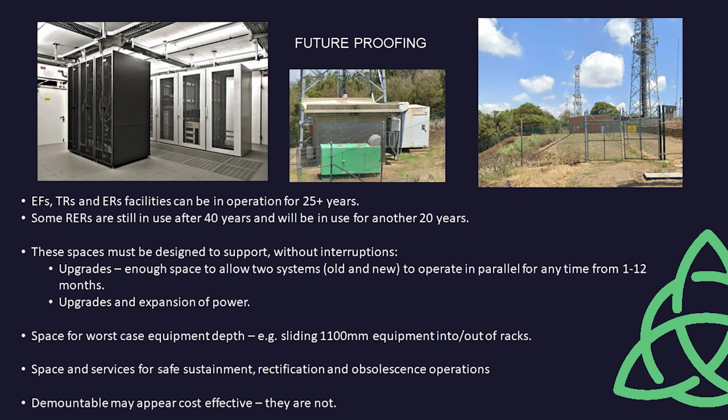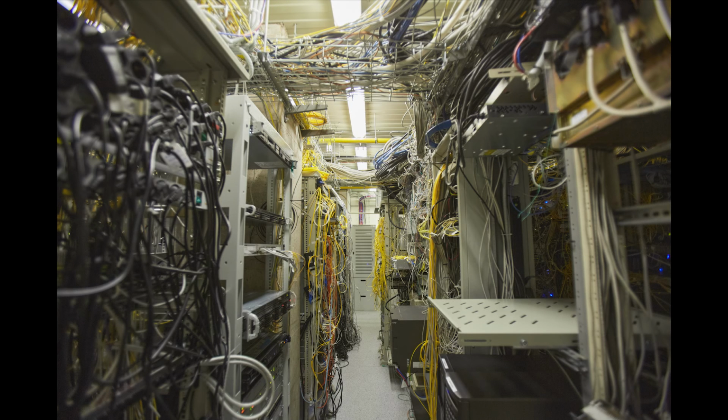Electrical distribution board location and other wall panel fittings, like security panels and cabling frames, must be coordinated to ensure that the above clearances are maintained. Additionally, the racks, when installed, must not prevent the doors of switchboards and other panels from being fully open for maintenance access. Any equipment room walls and doors on the outside of the respective building must be of construction capable of withstanding malicious vandal attack. Access should not be readily gained by removing panels or in-wall air conditioners.